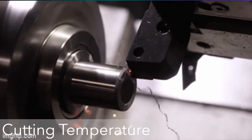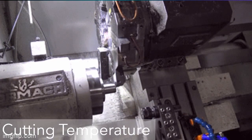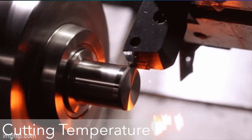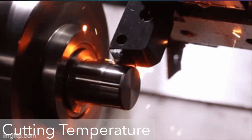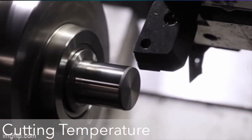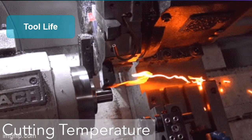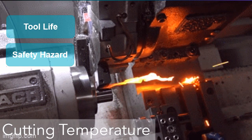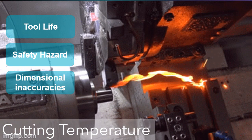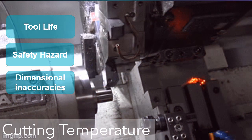Approximately 98% of the energy in machining is converted into heat, and about 2% is retained as elastic energy in the chip. This can cause the temperature to be very high at the tool-chip interface. The disadvantages of high cutting temperature are: first, it reduces the tool life. Also, it produces hot chips that pose a safety hazard to the machine operator. At the same time, it can cause inaccuracies in the part dimensions due to thermal expansion of the work material.